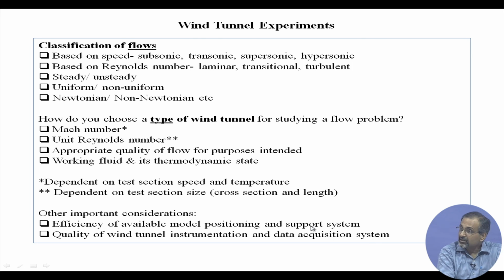The model support system. So you can support your system in different ways. You have looked at them. There could be sting mounted systems. You could be actually having other ways of mounting it through multiple struts which support the model and things like that. And also the quality of wind tunnel instrumentation. So that is another major issue, because whatever data you generate through the wind tunnel test, you are ultimately generating it through a system of sensors.